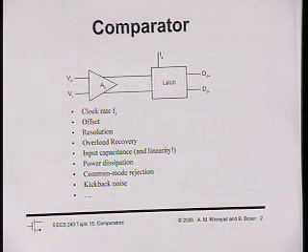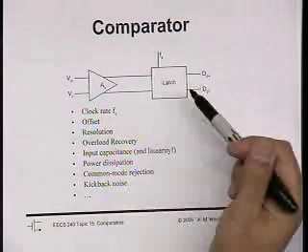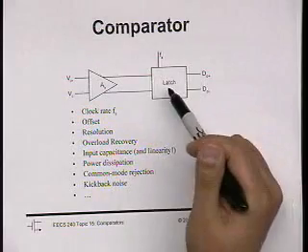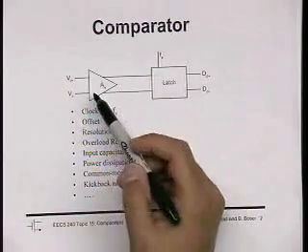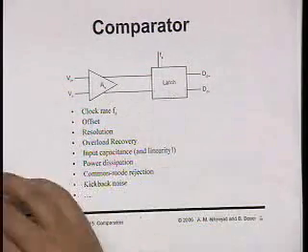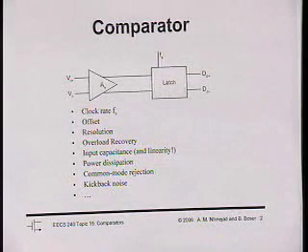Maybe like a buffer between the gain stage and your... Yeah, you're right. The latch has gain, so if I need gain, I can partition the gain between the input stage and the latch. All right. Any other comments? Why else would I use a latch?